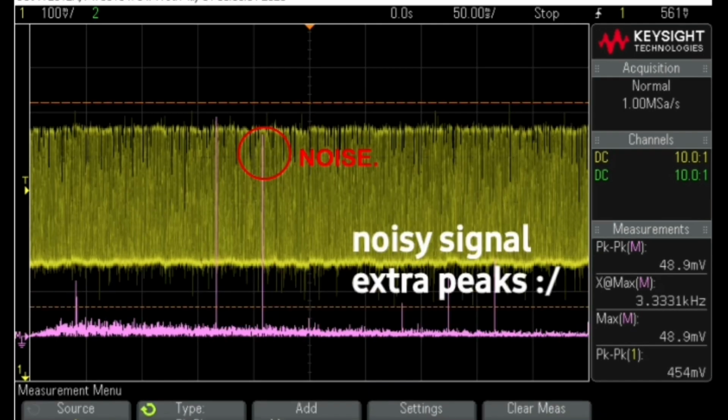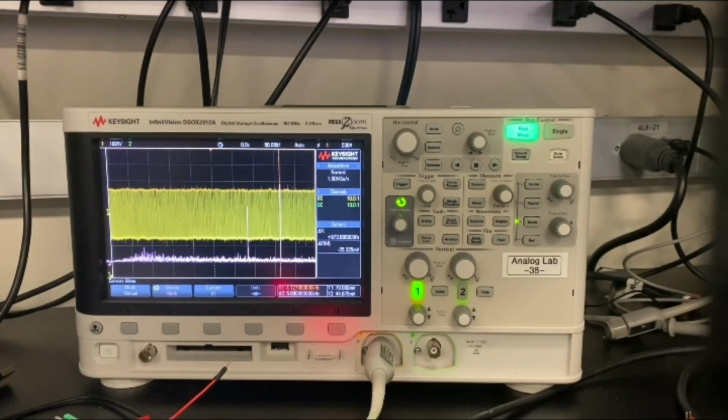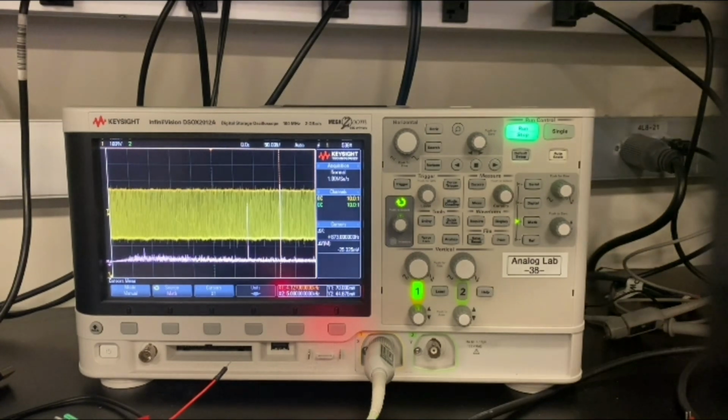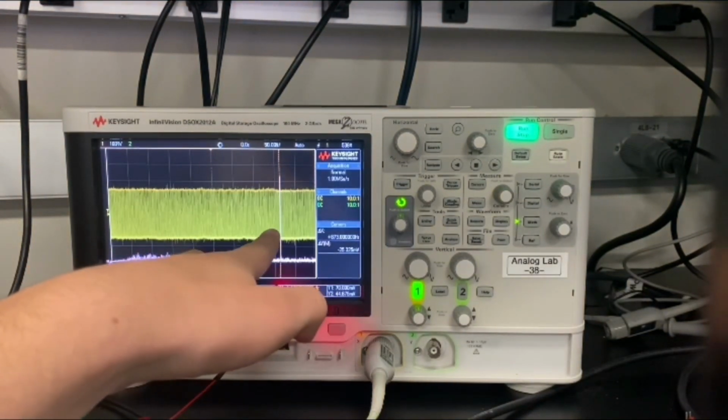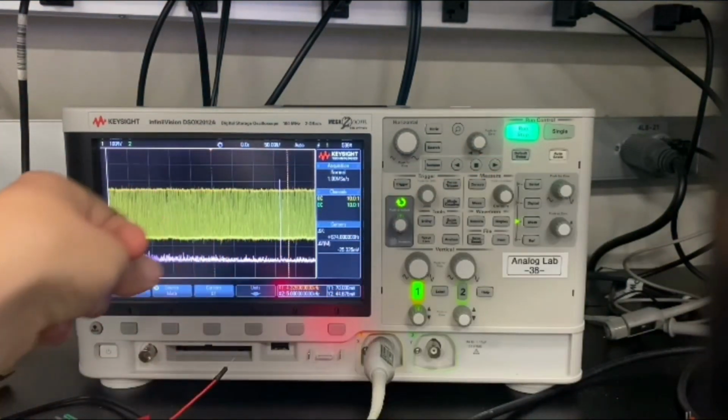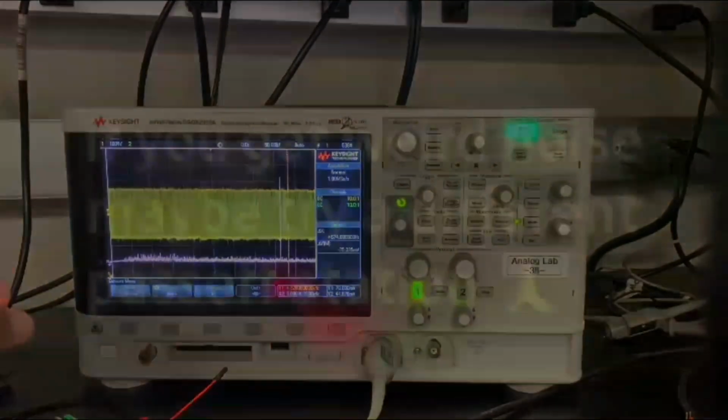So the way you can test that is by covering the photodiodes. You can see with the photodiodes covered, that signal that we were measuring goes away and this noise frequency stays there, meaning that you might just want to try it on a different passoff station.